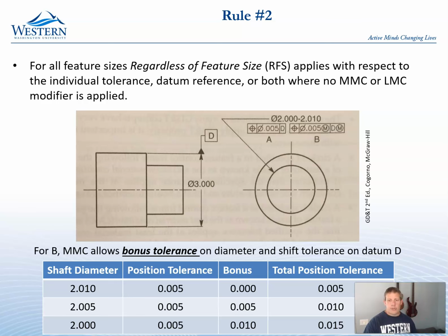And then in class, we're going to be doing some application of these. And then as we move through and you're doing your projects, I'm going to expect you to put good GD&T on your projects, and an appropriate amount. An appropriate amount means you put it where you need things to fit together, and where it isn't critical, you don't put GD&T, because the cost of measuring GD&T is pretty significant. So it's important to make things fit together, but you don't just add it on to look cool or whatever, to show your engineering chops.